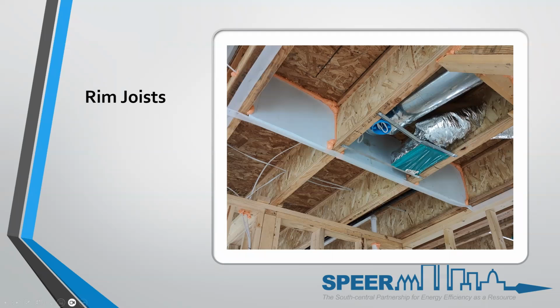A gasket's also been installed below that. As you can see, there's a white gasket being installed. So when the ceiling sheetrock gets installed to the garage, it will be air sealed at that band joist. Having it out of wood is fine, but it's never really cut correctly, and then not sealing that, it's hard to seal that up with caulking or poly if you're trying to put sheetrock up and then seal the gap. So putting a gasket below that, making sure that it meets exactly the same level as the sheetrock, means that that air sealing will take place.